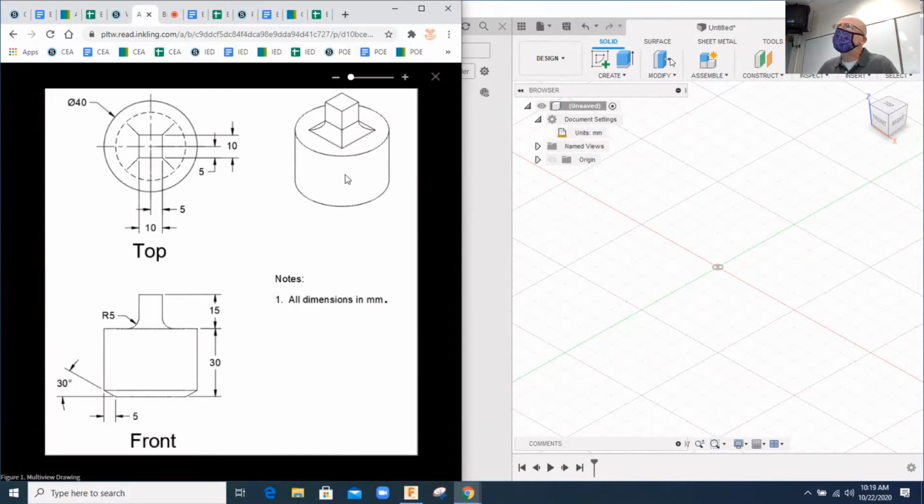What revolution means is that you take a two-dimensional sketch and then swing it around itself, and the sweeping motion turns that two-dimensional sketch into a three-dimensional solid piece. As I think about what I just said, a rectangle can be revolved around itself to make the cylinder, and that's what I'm going to do here. Think of a door on a hinge. If the door turns on the hinge, that sweeping action is what I'm talking about, except in this case the door would go all the way around.